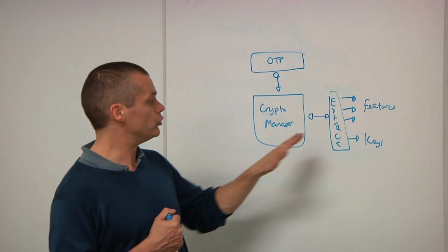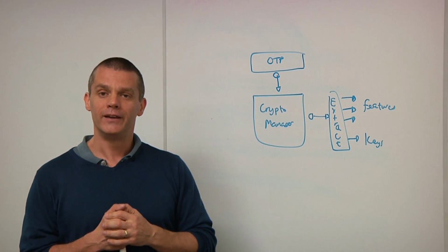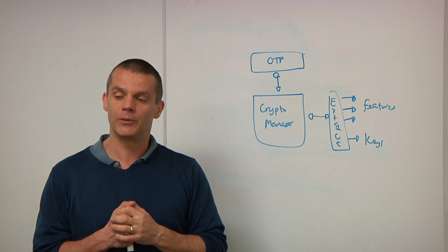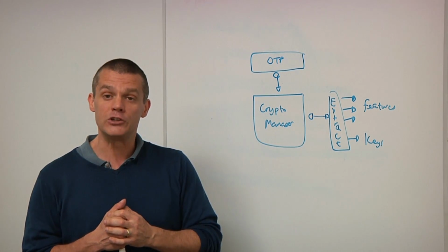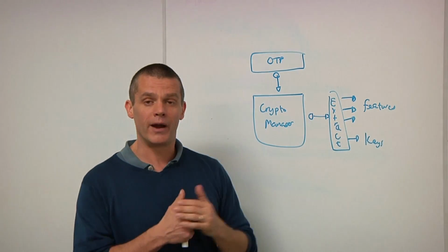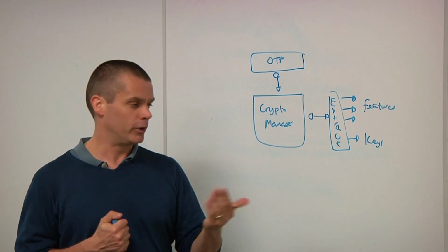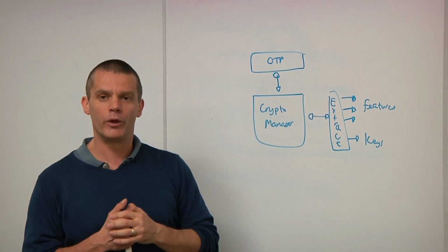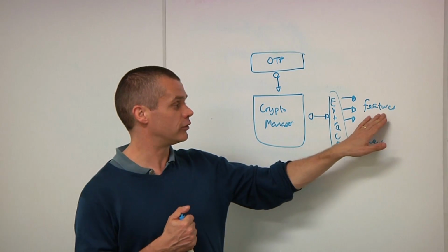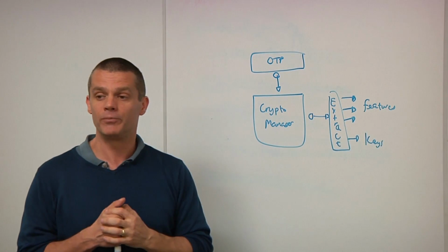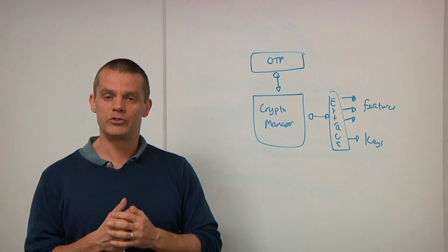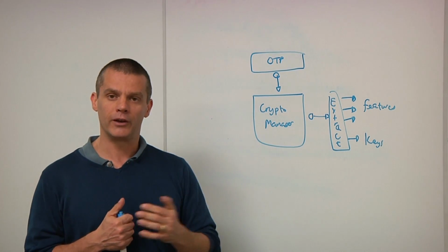What you can do with this integrated root of trust now is instead program those features and hook them up to this extractor function. And then the root of trust will turn the feature on and off. And it can be done dynamically, meaning, for example, one feature might be debug of the chip. And you can provide a command that's secured with the keys manufactured into the chip, that could be used on a one-time basis to turn on the debug option. Once you've used that command, it can't be reused. So now the next time the chip boots up, the debug feature will revert to being turned off again.